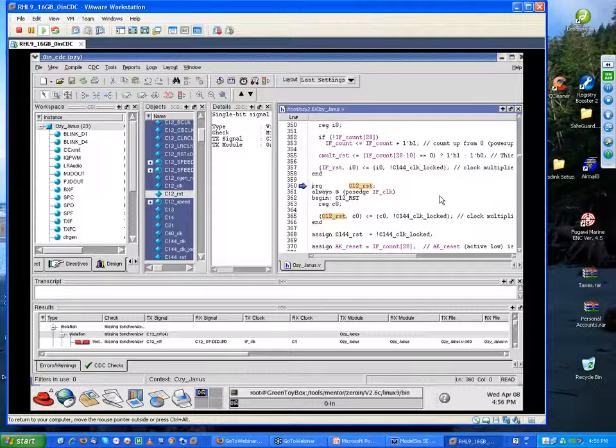So what do you notice here immediately about creating this C12 reset? That's a problem. Anything? Real short little statement here. I'm clocking it from a C144 clock domain, which is the 144 megahertz clock domain. I want to clock it into what I'm calling my C12 clock domain. So what's my problem?